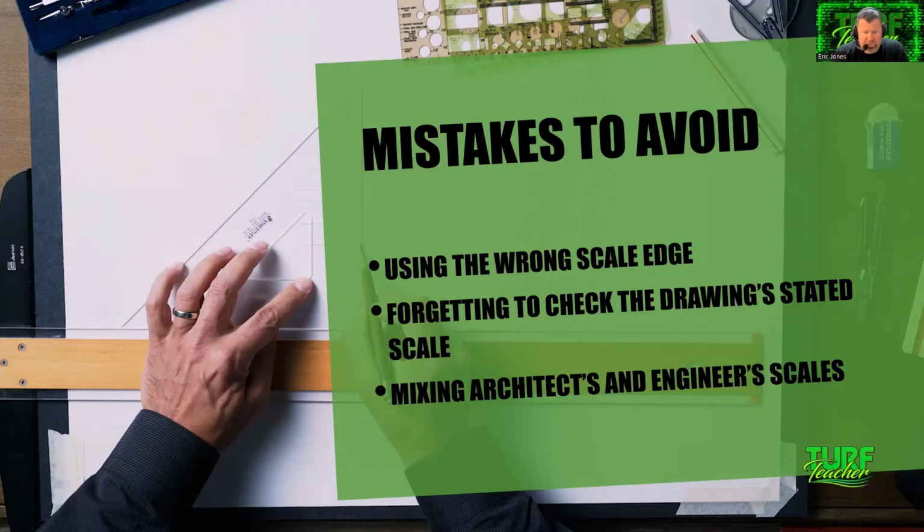Really, forgetting to check the drawing's stated scale. Yes, always look at it. Sometimes it may be a graphical scale. Sometimes it may say scale equals 1/8 of an inch equals 1 foot, or they may draw it graphically. Graphically, you can kind of trace over it if you're in the field and actually use it to help you measure in the field if you didn't have a scale or tape measure.